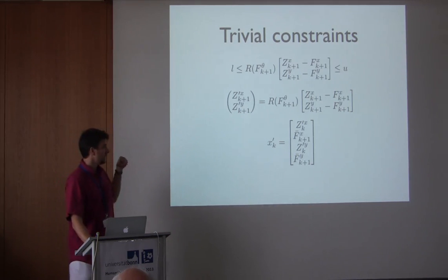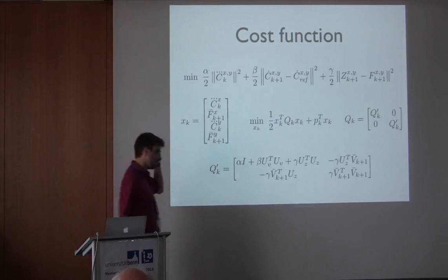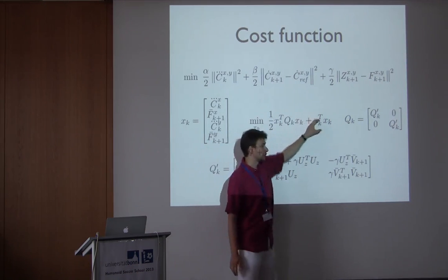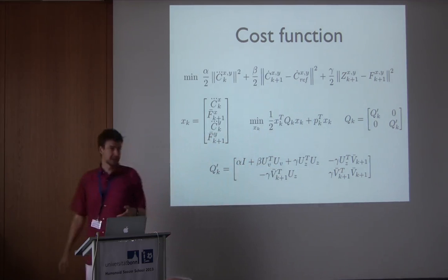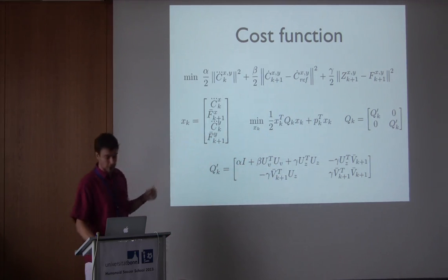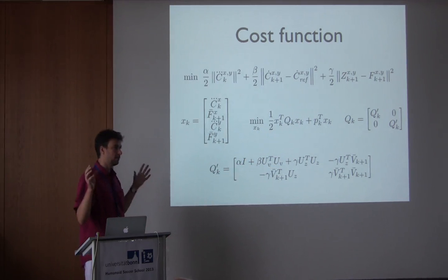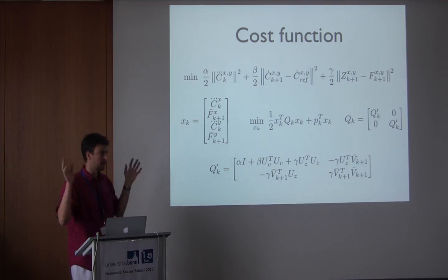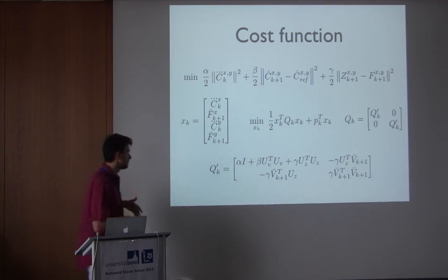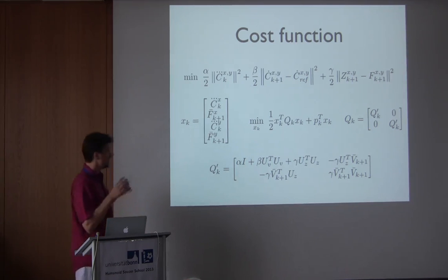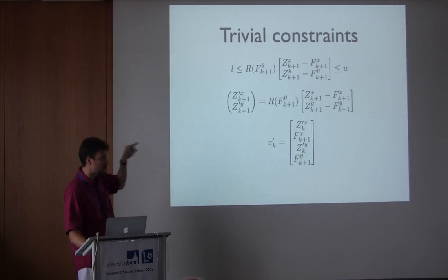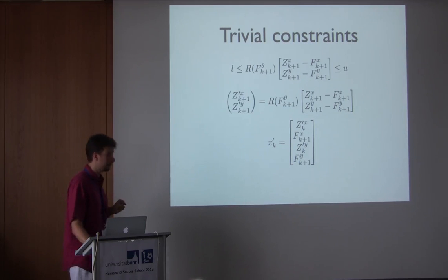Because, as I mentioned, the first proposition by Kajita in the ZMP control, he had only this function that he was minimizing. He said that's fast to solve. Solving this amounts to solving this linear equation, and I can pre-compute the inverse of matrix Q, and that's fine. Then I just have to make a matrix vector multiplication, or I can even go faster and find the solution. But you see here that introducing constraints, but making them trivial, can help you solve the problem even faster.